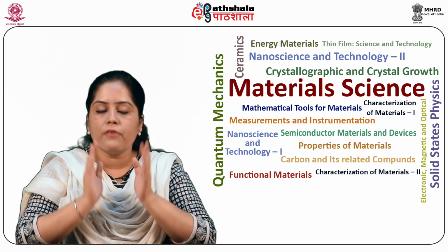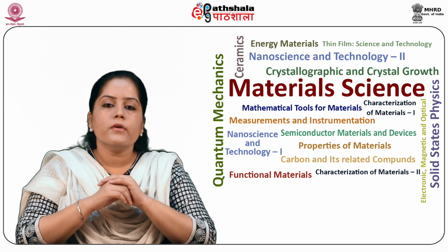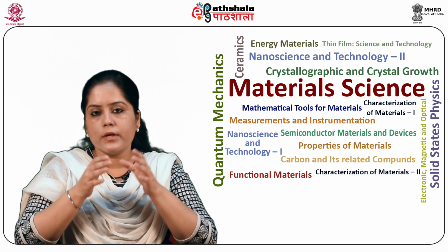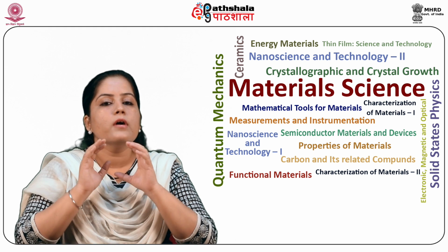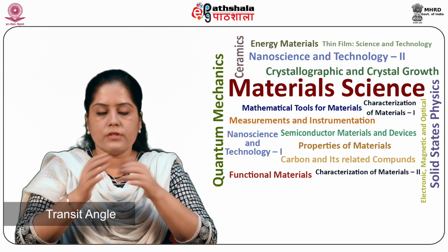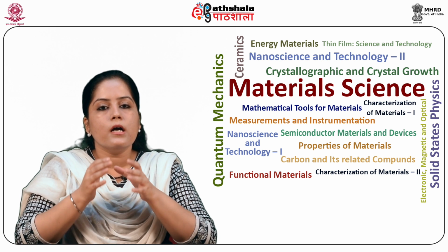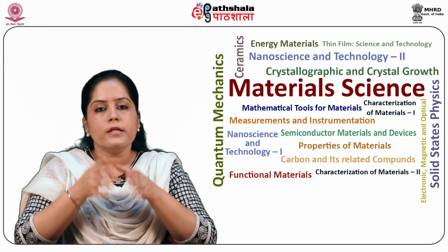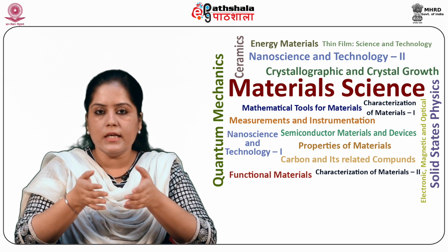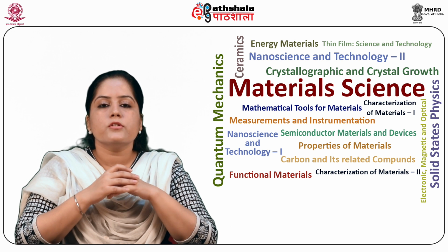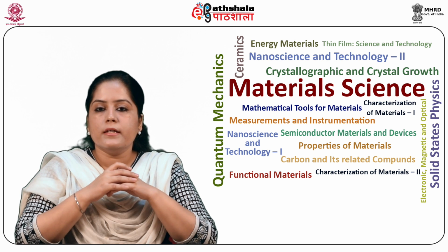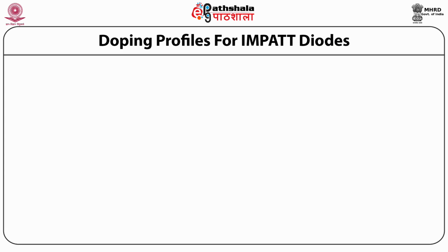of about 5 micron. We also find it useful to introduce the concept of transit angle, which is defined as theta_d equal to omega W_D by v_S or v_T, which is equivalent to omega multiplied by tau_T. Let us now discuss the doping profiles for Impatt diodes.